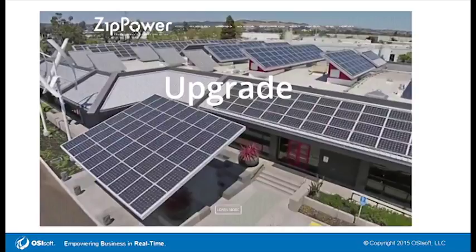But they have passive cooling in the building to open up windows at the right times and take cool in the air at the bottom and let hot air out at the top. They have heat swapping from the hot side of the building to the cool side of the building. So all in all, this building has been net zero as a retrofit for 2 years now. But that's the upgrade component.